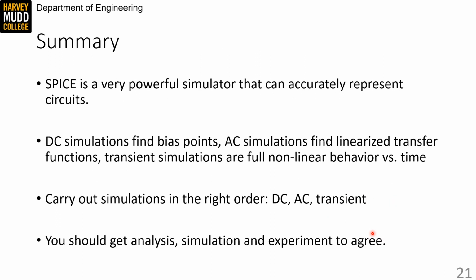So in summary, SPICE is a very powerful simulator that can accurately represent circuits, and you should consider yourself to have access to it. You should use it in order to solve your problems. DC simulations find bias points, AC simulations find linearized transfer functions, and transient simulations are full nonlinear behavior of a circuit versus time. Make sure you carry out your simulations in the right order, which is almost always DC, AC, and then transient.